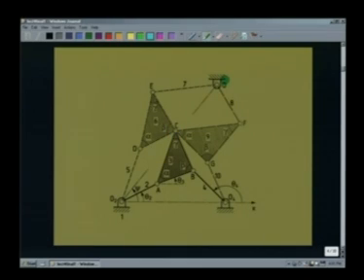There is a second 4-bar linkage consisting of links 1, 8, 9 and 10 with the same coupler point C, and the third 4-bar linkage consisting of link number 1, that is the fixed link, link 7, link 6 and link 5. Now all these three 4-bar linkages have the same coupler point C, and this assembly moves in a unique fashion. In other words, there are three different 4-bar linkages which can generate the same coupler curve at the point C. As a result, this gives a wider choice to the designer to choose one of these three linkages to produce the same coupler curve.